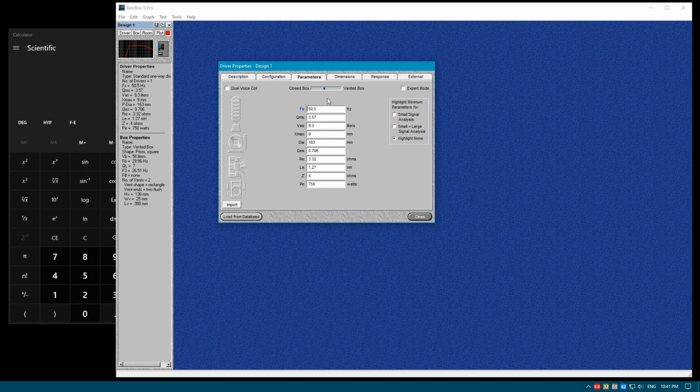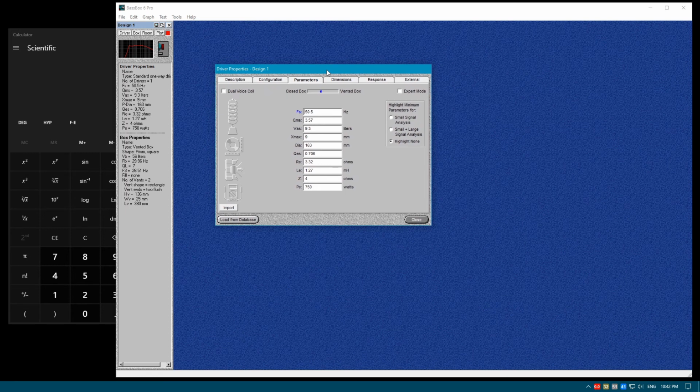One option I used was the DATS, which is a Dayton Audio measuring system. It's like an inbuilt oscilloscope and driver and bunch of measure resistance and capacitance. You can basically get all the parameters of a speaker pretty quickly and easily.